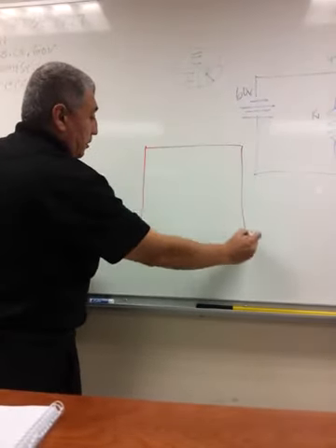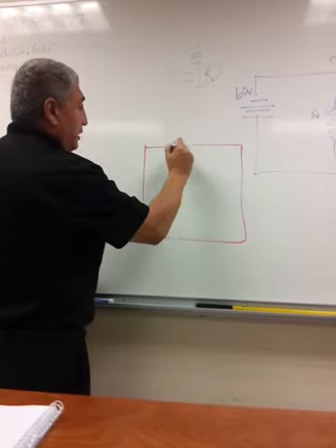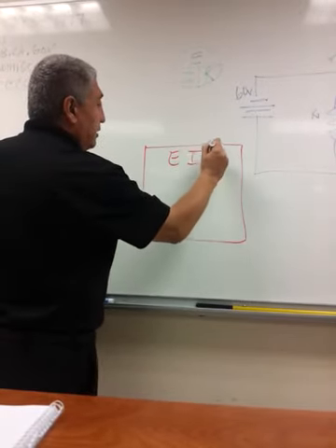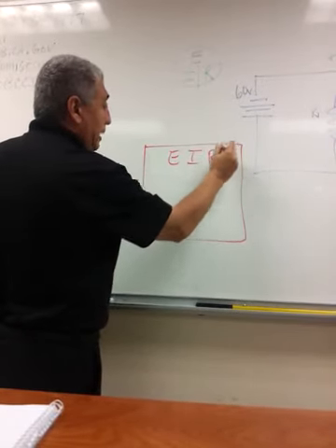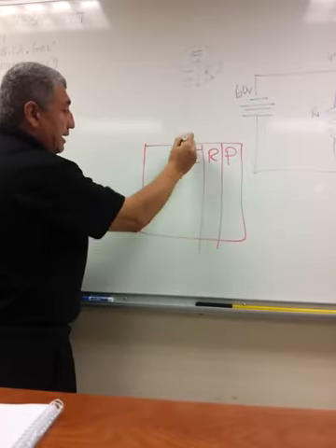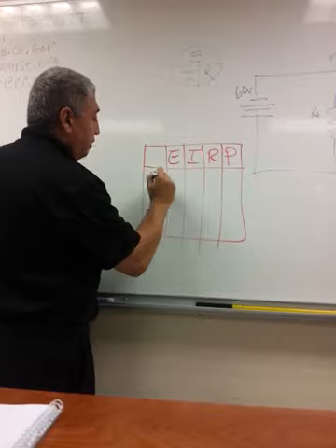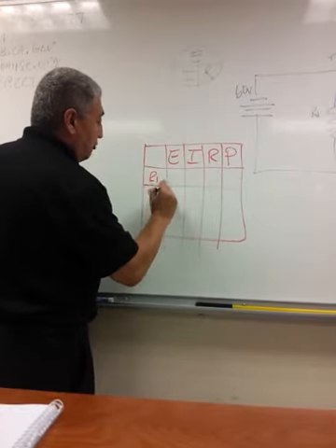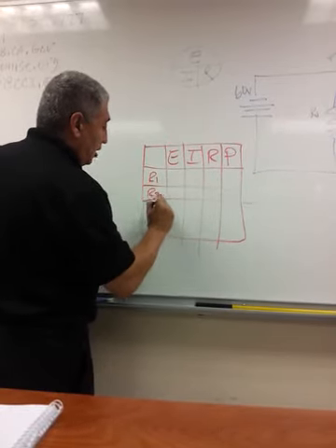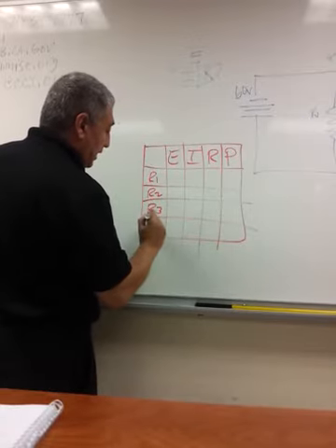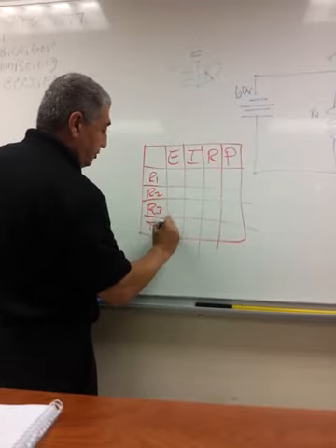Let's go ahead and build our answer grid, and we'll show our voltage, our current, our resistance, and our power. We'll go ahead and make a column for each one. We also want to show resistors R1, R2, R3, and our total values.